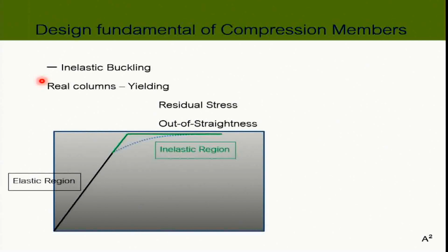And the relationship between the stress or the force and deformation is generally linear. Okay? And so if our structure behavior is in the elastic region, that would mean as soon as we unload the structure, everything should go back to normal.